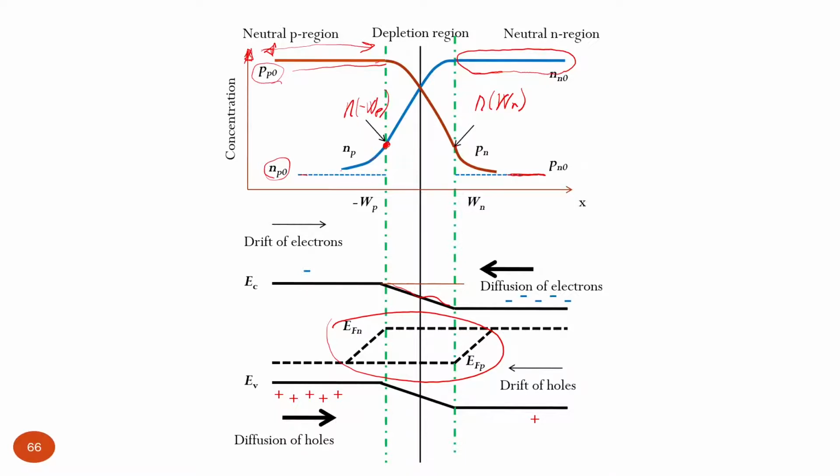The concentration of acceptors and donors in this region is kind of linear, yeah? That is a good question, because the depletion region is by definition such that this strong electric field does not let charge carriers stay there for long, so they don't establish any kind of equilibrium condition there, and if some charge carriers appear in this depletion region, they are efficiently extracted.